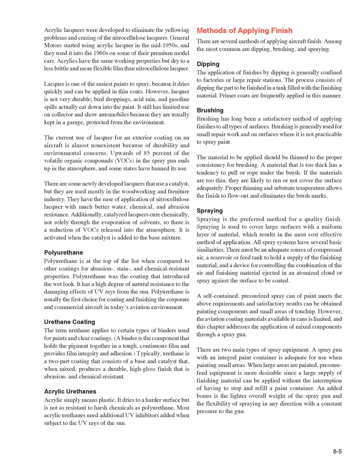The material to be applied should be thinned to the proper consistency for brushing. A material that is too thick has a tendency to pull or rope under the brush. If the materials are too thin, they are likely to run or not cover the surface adequately. Proper thinning and substrate temperature allows the finish to flow out and eliminates the brush marks.